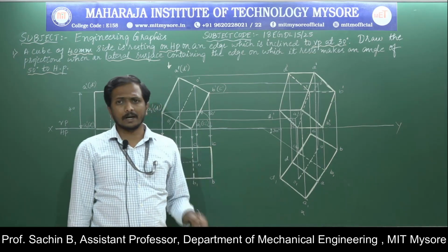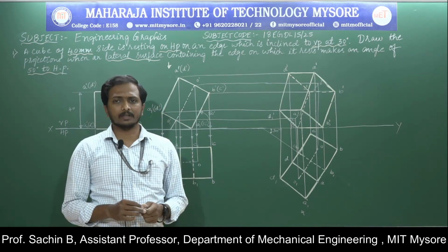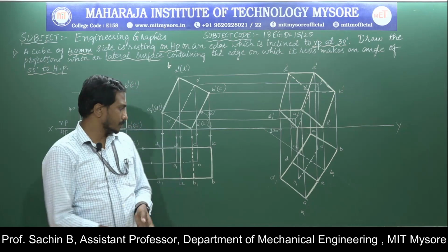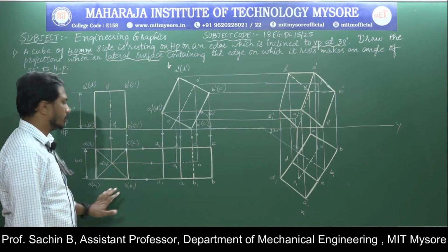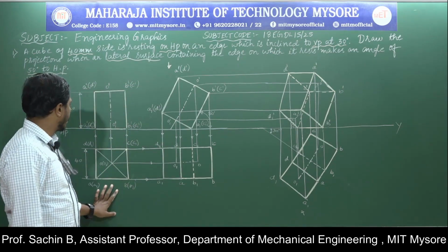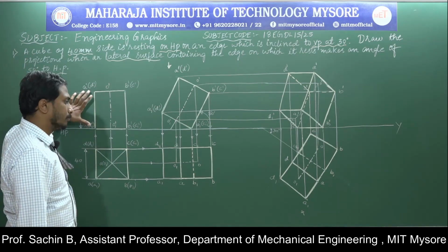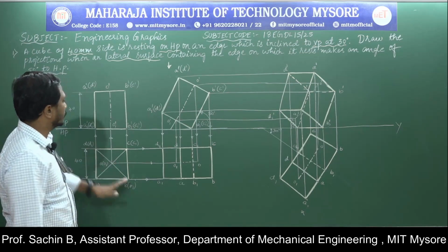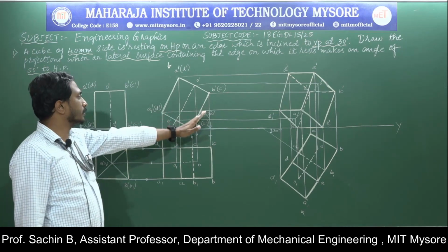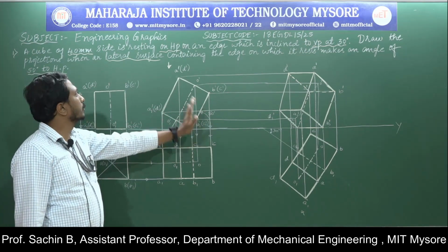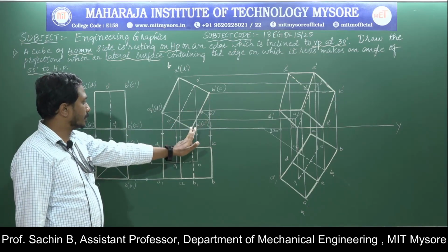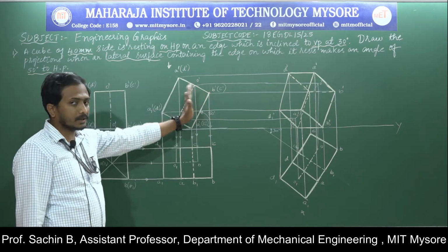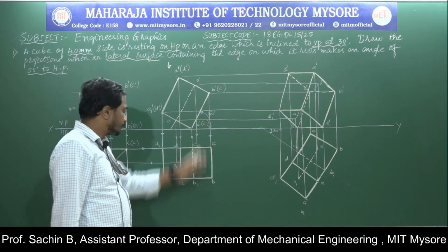Okay, this is regarding the cube problem when it comes to the special case problem. First, the 40 mm sided top view is constructed. Again the length of the cube will remain the same because it's a regular polyhedron, 40 mm length. Next I will go for inclining the resting edge lateral face surface, means for this edge the lateral surface, to an angle of 50 degrees.